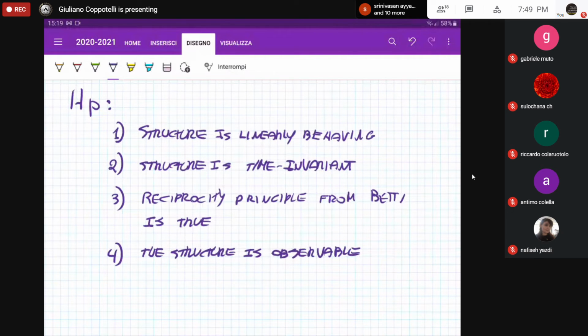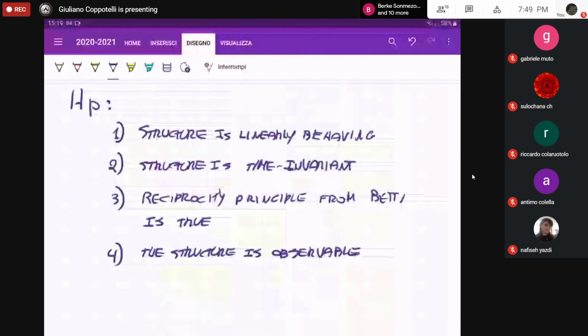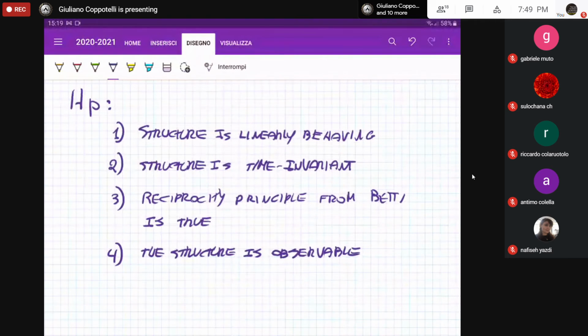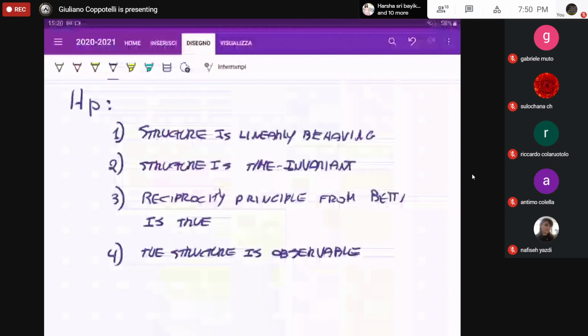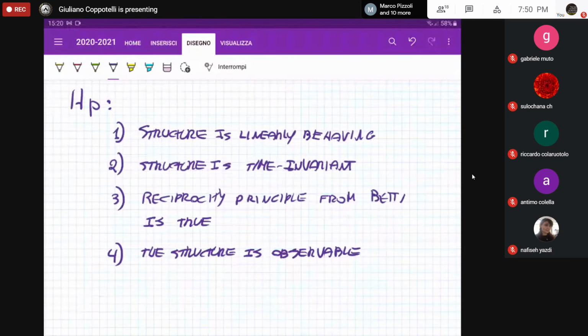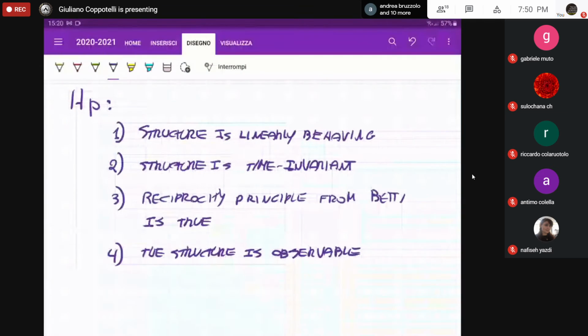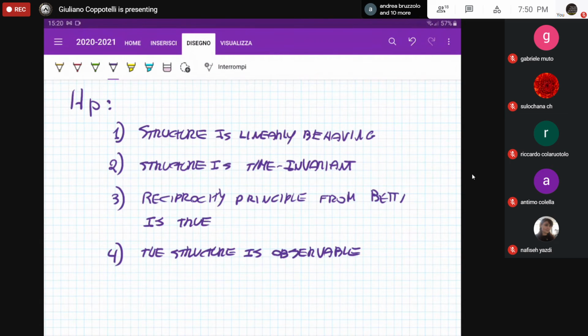The same discussion could be done also when referring to space rockets. Space rockets, as you very well know, in let's say one to two minutes time, lose practically all their mass, 70-80% of the mass, even more. Therefore we are not considering that structure for the whole mission time, but we are considering a piecewise analysis of the different parts composing the mission, and for each part I am assuming that the system is characterized with constant mass and stiffness.